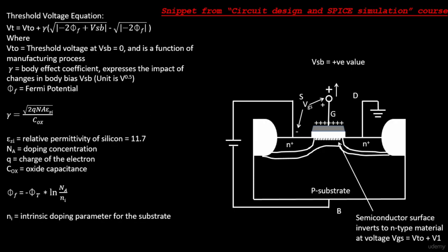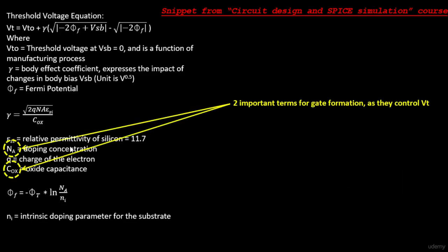The next step is to expose this photoresist to UV light. The same thing happens: the light doesn't react with the resist which is under this area. It only reacts with the area which is exposed. And then once you wash it in a solution, this particular area of your photoresist gets washed away. Okay, so now this area is available for any chemical reactions that we have to do over here. The next step is to remove the mask itself, and finally you have to create a P-well over here.